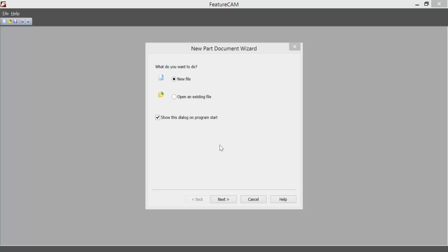The reason for this, it is a lot easier to set the tool to the bottom of the vise and get consistent thicknesses on various pieces that will be in the vise as opposed to setting our tool to the top of every part. Every part may not be the same thickness that we put in there. That means our tool lengths would change for every part that we put in. Gets tedious. That wastes a lot of time.